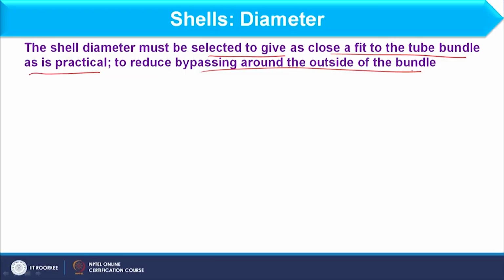Now if you remember the classification of shell and tube heat exchanger, we have discussed that clearance is maximum in internal floating head, because the whole tube sheet is lying within the diameter of the shell, right. So in that case clearance is very large. So once I am having the large clearance, I have to invest a lot in shell diameter.